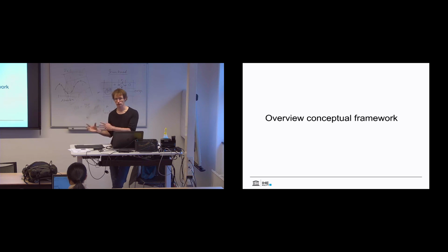So if you do a refinement somewhere else, or you do more refinements, it means different boundary conditions. That means a new bathymetry. That means you have to redo everything. Well, if you use flexible mesh, for example, then you can keep your boundary locations at the same position, and you can change your grid locally. That doesn't matter, and you can still use the same boundary. So you can shift your grid, refine it, you can cut out pieces, you can do whatever you want. But you don't have to remake your bathymetry, your boundary conditions, your grid.